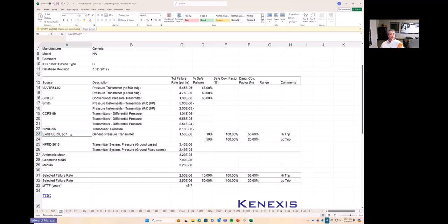And you'll notice that the data from here we didn't use. And you see that? OREDA. And in this case, I'll show you in just a second, the data is not that good. So we actually have to go and critically analyze each one of these data sources to determine how was the data collected, how much data was collected, what is the environment that the data is collected in, is the data point even valuable enough for me to put onto this spreadsheet for further consideration.